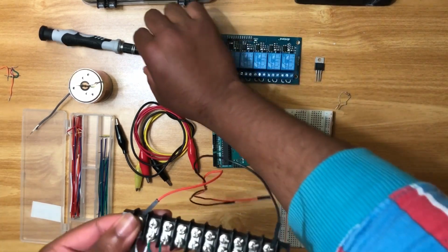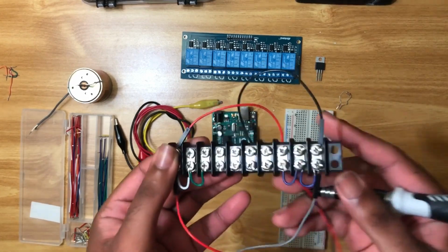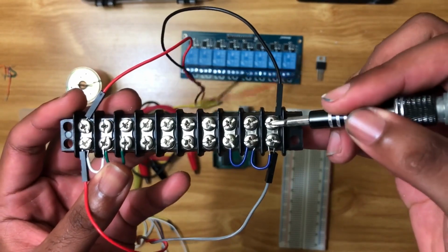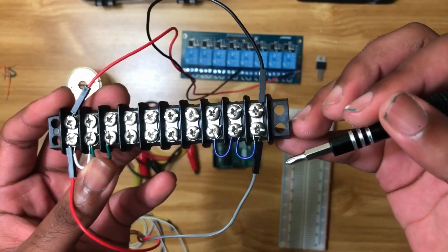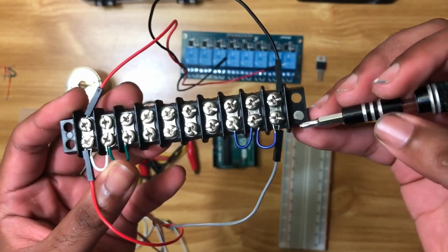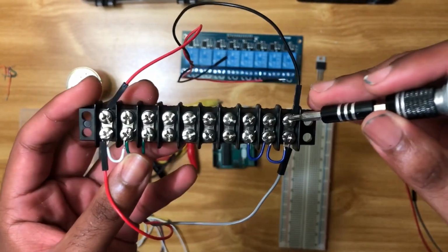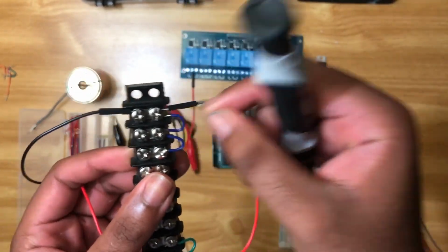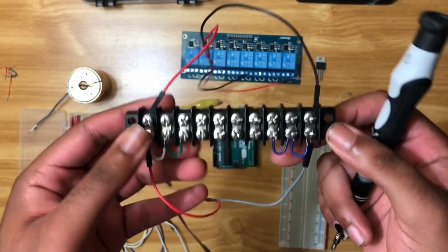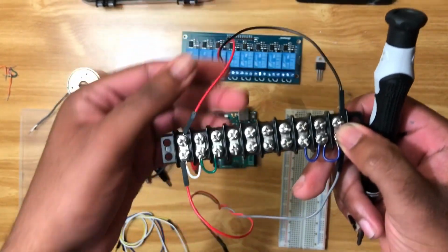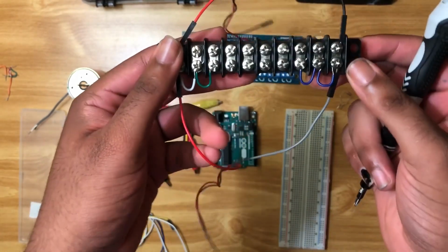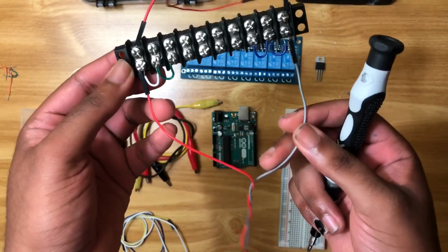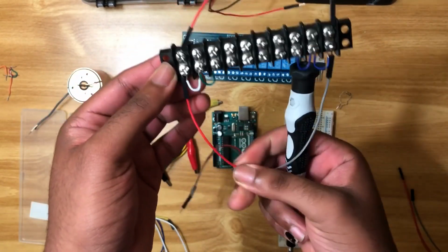And this is just a very simple device where you have these screws that are all connected, these pairs of screws that are connected to one another by a plate underneath. And we can connect each of these pairs like this with these wires. And what that allows us to do is we can distribute power to multiple devices, right? So if you imagine we had a power source on this side, and this side was negative and this side was positive.